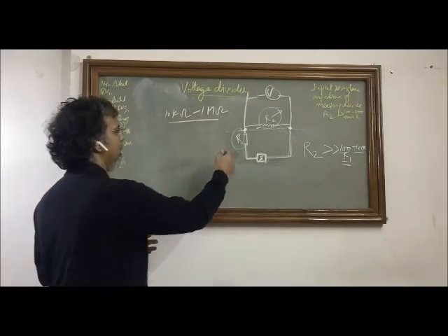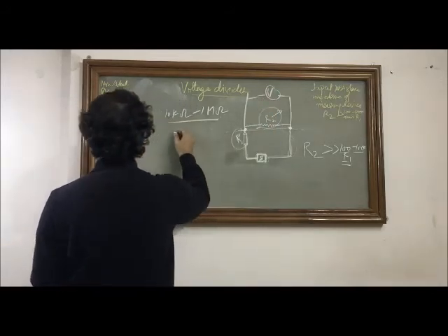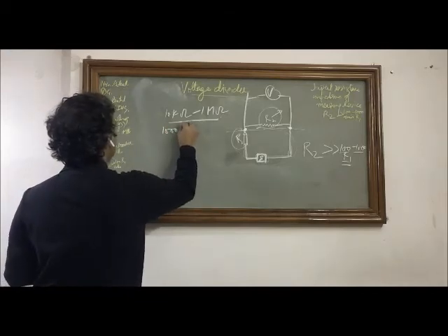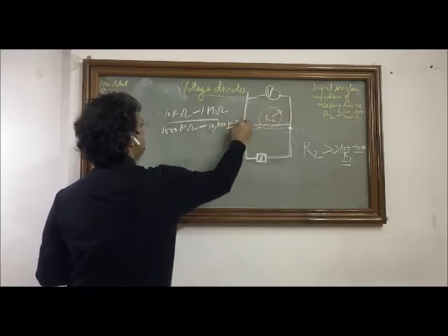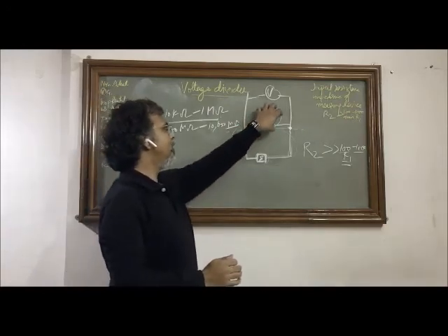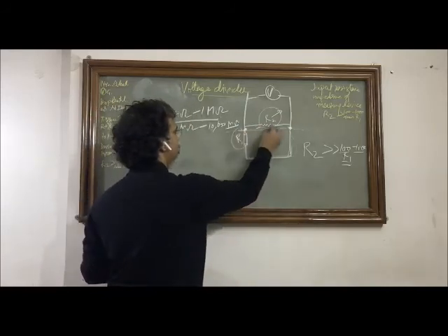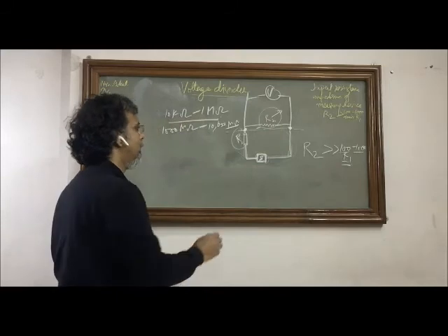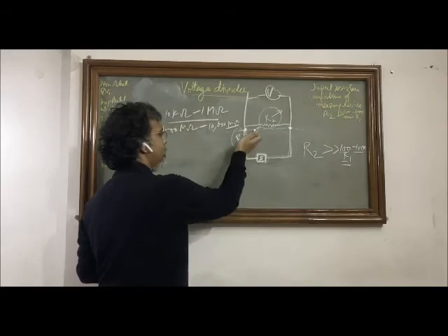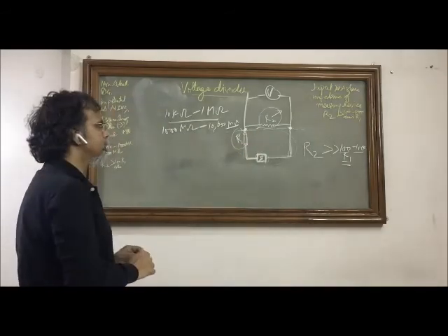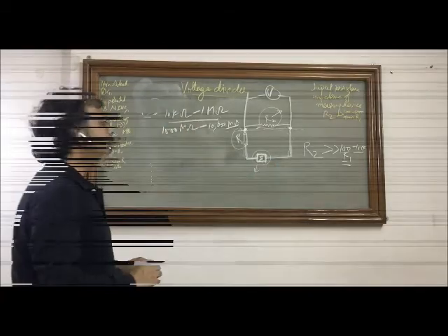And now we know that we have to keep the resistance of the measuring device at a very high value. So we normally keep the resistance of this measuring device, which is put across these 2 points, from 1000 mega ohms to 10,000 mega ohms, so high that we can assume the energy consumed up to the skin is so low that it is almost equivalent to the energy available at this potential difference of the biopotential generator.